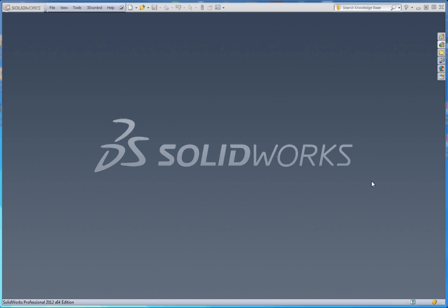We're going to apply a 2 unit after the decimal place precision on that. But in difference to the book, we're going to go ahead and apply dual dimensions to that. We're going to make the dual dimensions up to 3 units after the decimal. And then we're going to name it ultimately part-mm-ANSI. So let's do this.